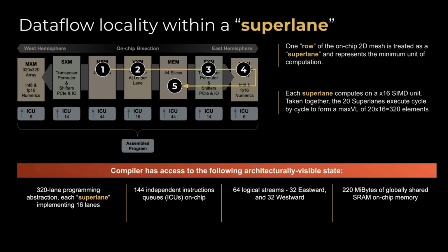And then lastly, we take that and we install those weights into one of our deep learning matrix units. That matrix unit is what produces your output features, which are the results that flow back at time 5 here and get written back out to memory. So you can see how this contrasts with a conventional CPU, where you do a load from DRAM and move it from DRAM to the last level cache, and then from the last level cache to the next level cache. From there, finally, you make 3 or 4 implicit moves to get it into your general purpose registers, where you can then do something and hope that it doesn't get a cache eviction.